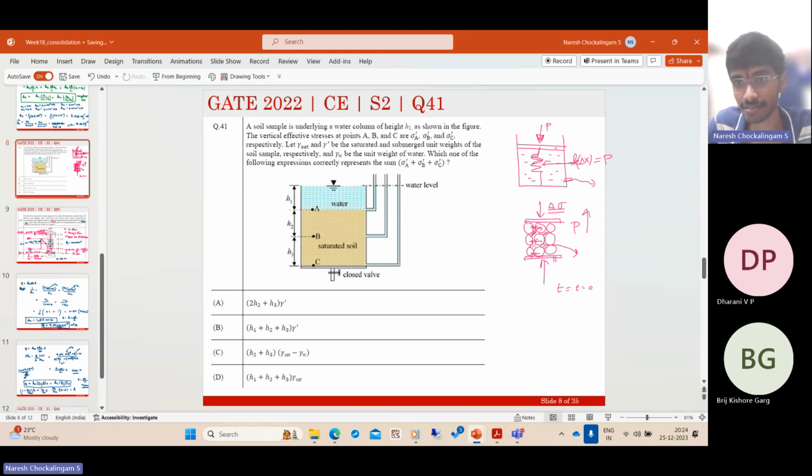So in this model, if sigma is the total stress that is applied to the soil, a part of it is taken by the soil skeleton in the form of intergranular forces. One granule presses against the other, and the other part is taken by the pore pressure U. This part which is effectively resisted by the soil is the effective stress, and this is the pore pressure.